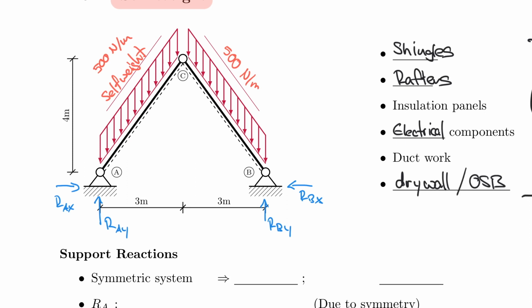It is very common initially to overlook the X components. The vertical is clear because everything that goes up has to come down. So these two balance pretty much everything that comes down. But because of the hinge here, if these were rollers, you can probably imagine that they would just slide out. Therefore we need something to prevent that. So we need RBX and RAX.